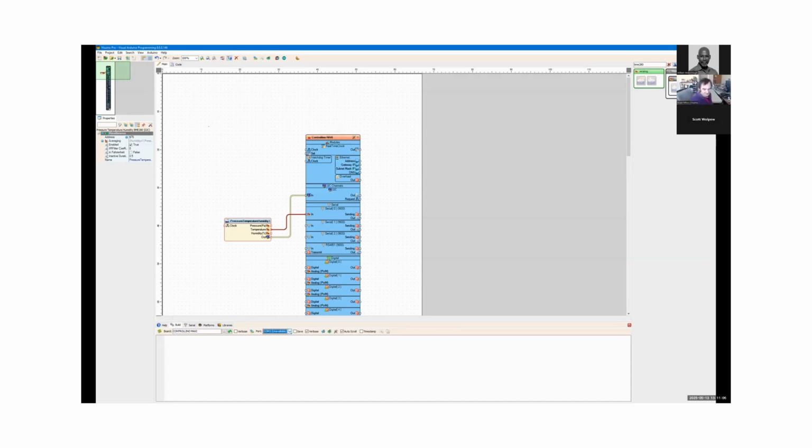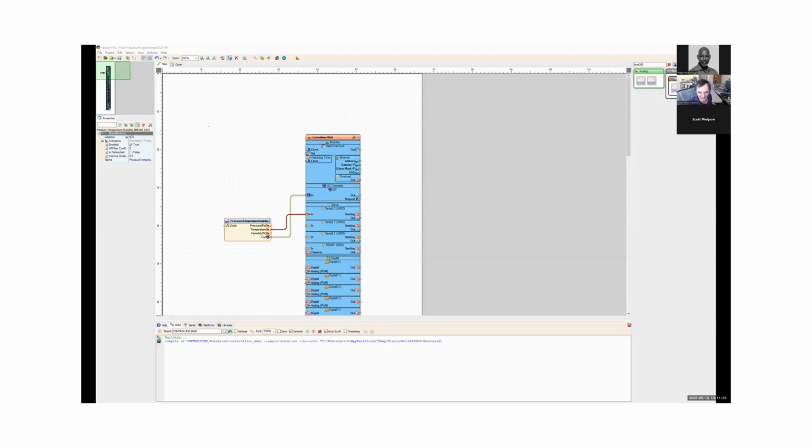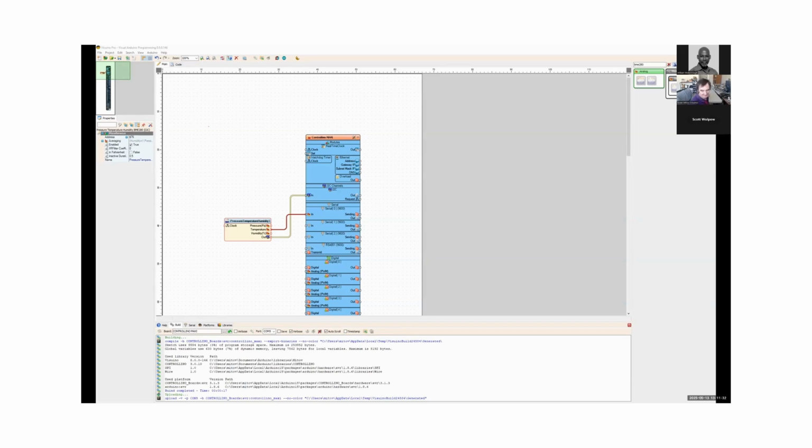So I'm connecting the USB port, and this is COM port 5. And now we can compile and upload the code. I have connected two sensors. It's uploading. We can look at it. So I have connected two sensors. I have connected the pressure, humidity, and temperature sensor, and I have connected light sensor here. The light sensor is a simple analog light sensor.